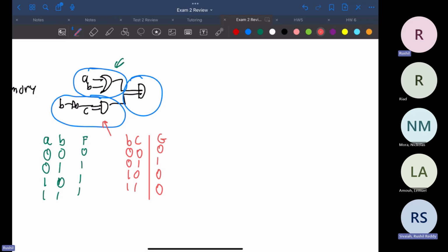With these, you always combine the NOT gate. There's no reason to have a LUT for just an inverter. That's just a waste of gates.